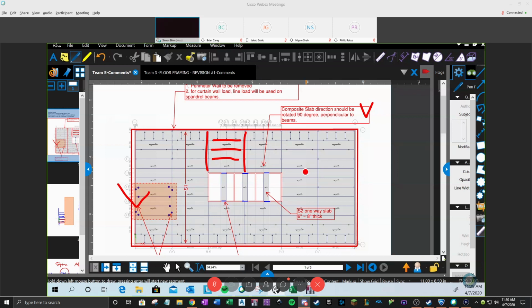And obviously girder and slab depends on which girder you're looking at. It is mostly parallel, like this. So you should always understand which one is the filler beam and which is the girder. And luckily the metal deck sits on the filler beams.